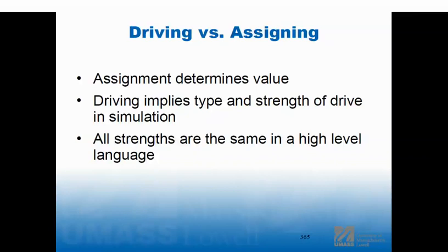When you look at the tri-state driver output on the logic, there's two pins. There's the output, and there's the tri-state control. Those are two inputs to the I/O block, which come out to one pin. Now, there could actually be three. There could be an input, and this is a bidirectional pin. So now that pad has three connections: the output enable, the output, and then an input coming in from the pad.